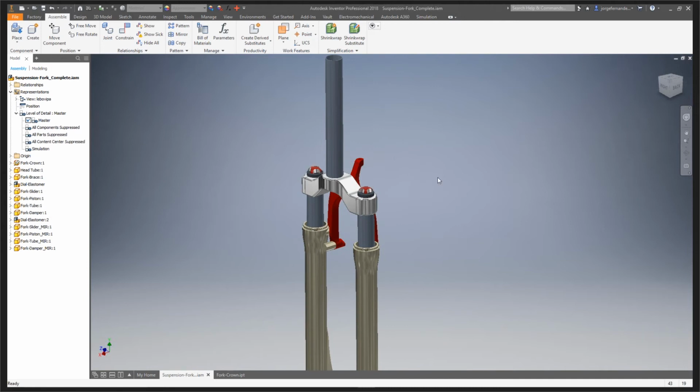That is, of course, I could do an assembly as well. Right now, we'll keep it straightforward at the one part, but we could come in here and use contacts and make sure that everything's set up with this sub-assembly or more if we wanted to. Sometimes, again, if you just want to get a rough idea, it's good to open up the part, apply it, and see what works. We would still be able to use levels of detail inside of Inventor here to exclude everything else in just the one part.